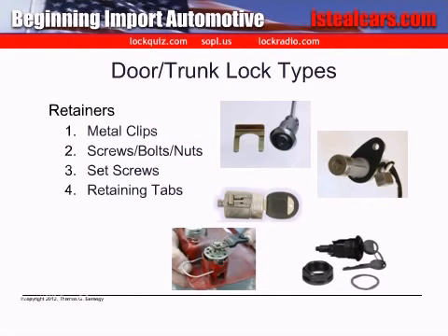Less common are locks held in place using retaining tabs. The door locks on early model General Motors trucks had a piece of spring steel swedged or staked to their side. This piece served as a locking tab for the lock that, once inserted into its pocket or sleeve on the door handle, held the lock in place. To release the handle, the lock had to be removed and the lock's retaining tab had to be depressed through a small hole located on the side of the lock's pocket.